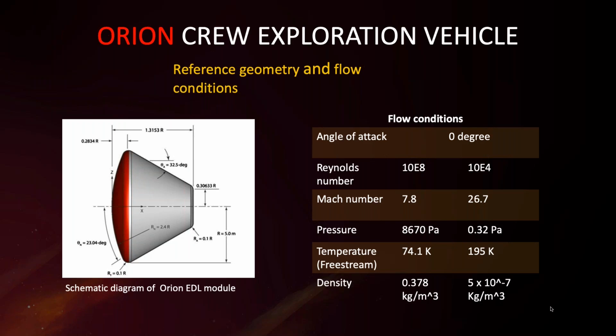Oh yeah, there was some issue with the symmetry condition, and that's why we did 2D simulation. We even raised the issue in the forum once. When the symmetry condition is used, there was some issue with writing out data also. So students were complaining, and we switched from axisymmetric simulation to two-dimensional simulations. It was rightly pointed out that we faced some issue with the symmetry condition, and it seems that in the latest version of SU2 the issue has been fixed, because the simulations run by the students with the latest version do not seem to have issues with writing out data and so on.